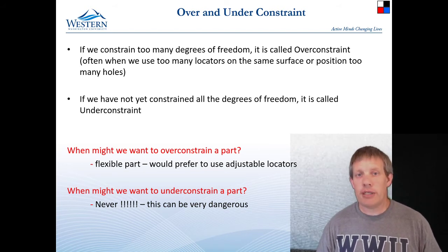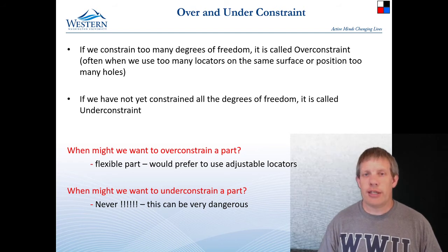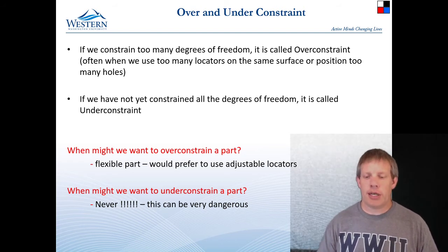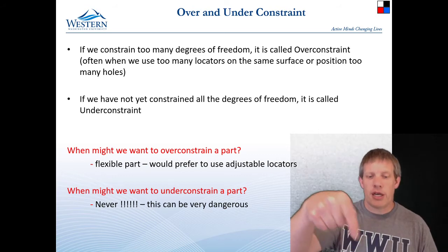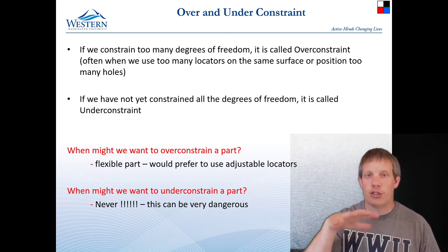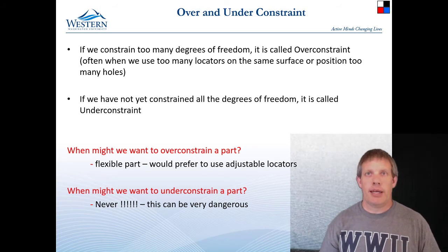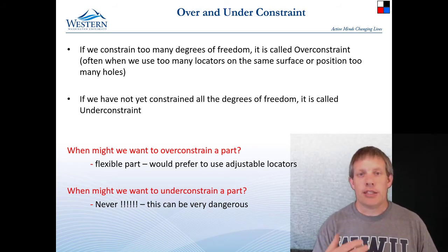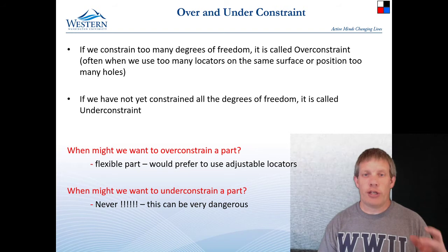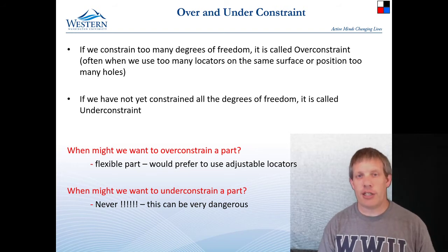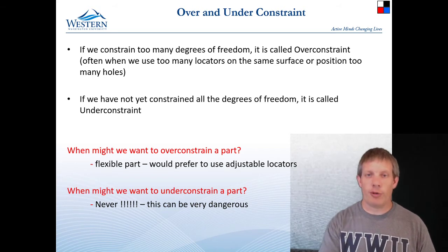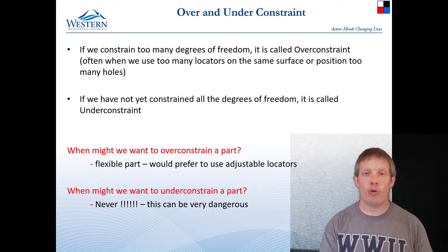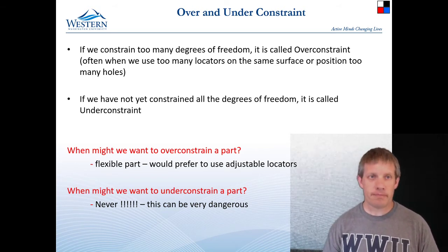Occasionally in measurement, like with the coordinate measuring machine, we will under constrain the part, and the reason is because the very first thing that we do with the CMM probe is come in and touch all the edges to locate the part. But it is a slow method of doing things when we could have put the correct location in place and then not had to find the planes before we started measuring the part. We would just know where the planes of contact were.